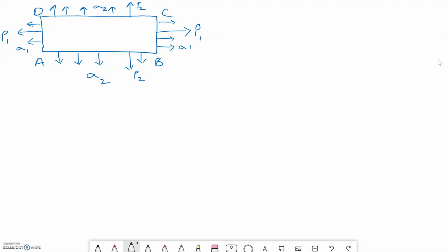All right. Now we are interested in an oblique plane and what kind of stresses are applicable in this oblique plane. Let us assume a plane FC which is at an angle theta with BC.